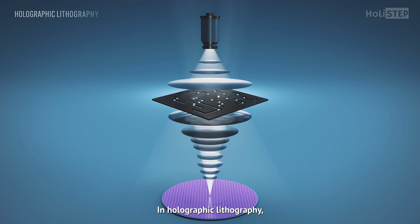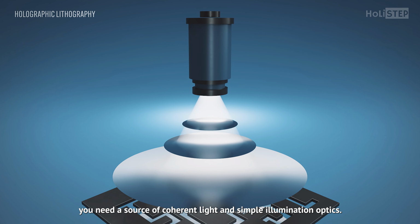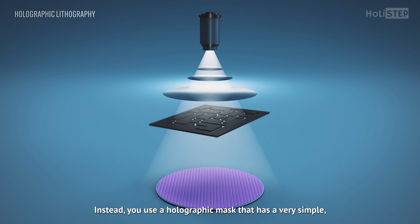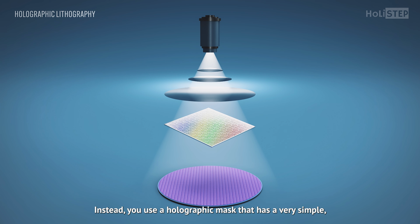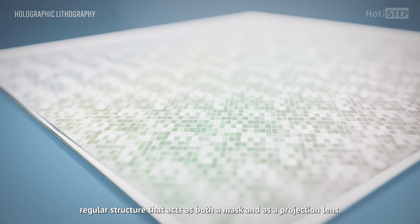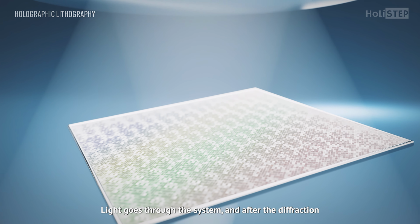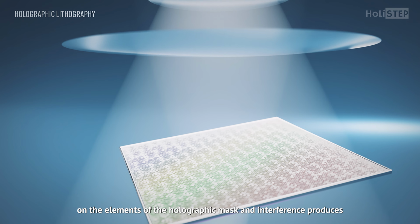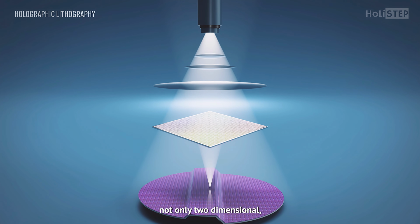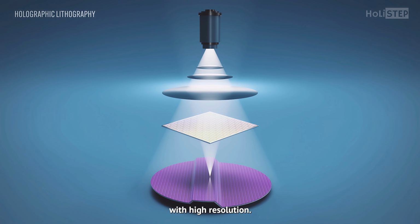In holographic lithography, you need a source of coherent light and simple illumination optics. You do not need a projection lens. Instead, you use a holographic mask that has a very simple, regular structure that acts as both a mask and as a projection lens. Light goes through the system, and after the diffraction on the elements of the holographic mask and interference, produces not only two-dimensional but also three-dimensional structures at one exposure with high resolution.